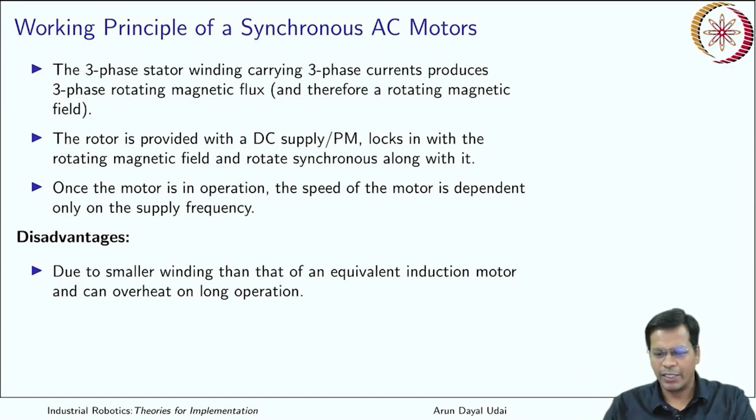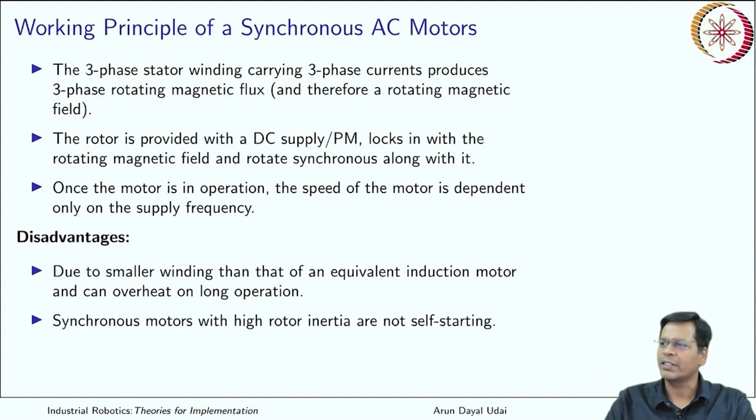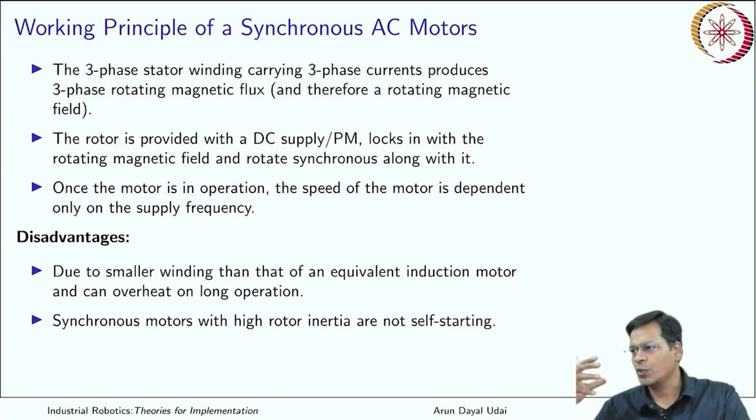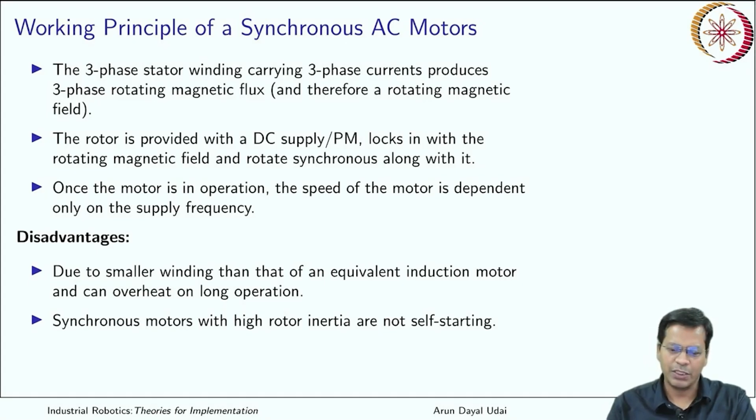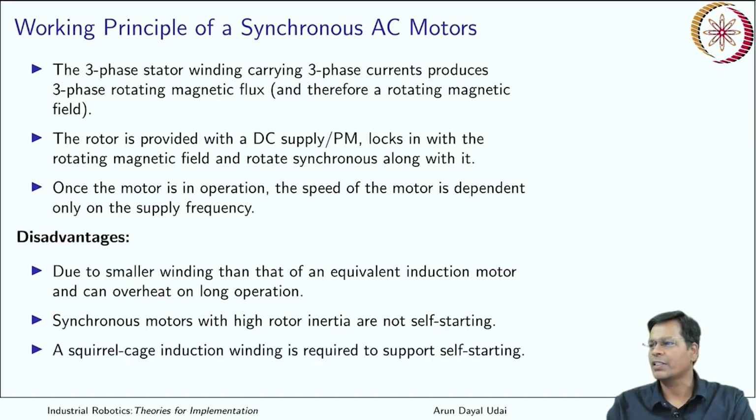So you need to have a good arrangement to dissipate the kind of heat which is generated while it is running. Synchronous motors have a high rotor inertia because it has magnets, either a permanent magnet or maybe some exciter coil, so that makes it very heavy. That is the reason it doesn't pick up speed immediately on applying a rotating magnetic field. So they don't have any self-starting capability.